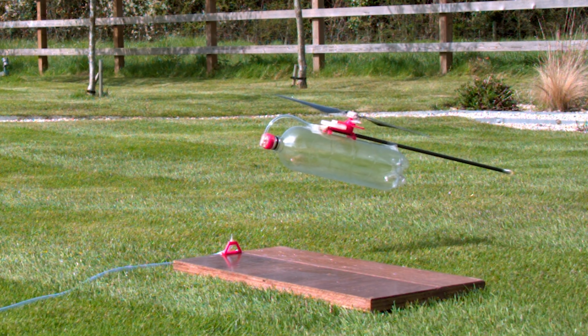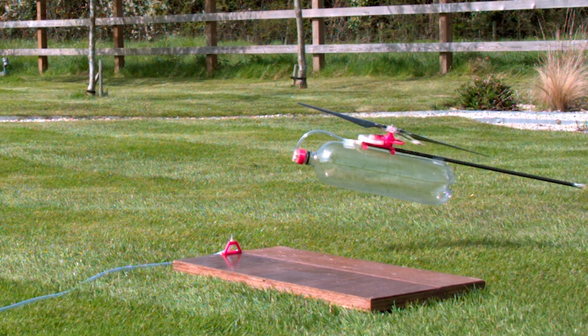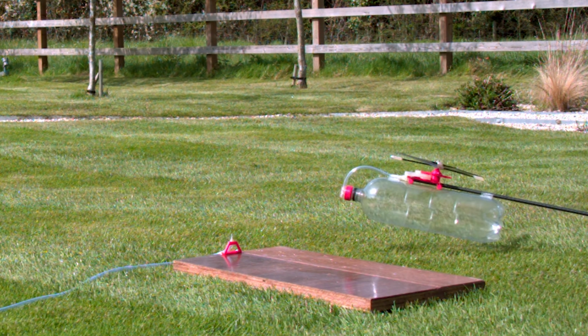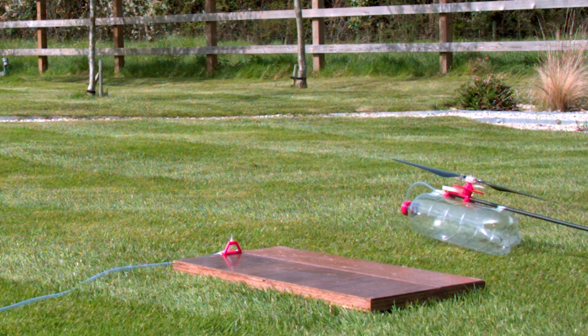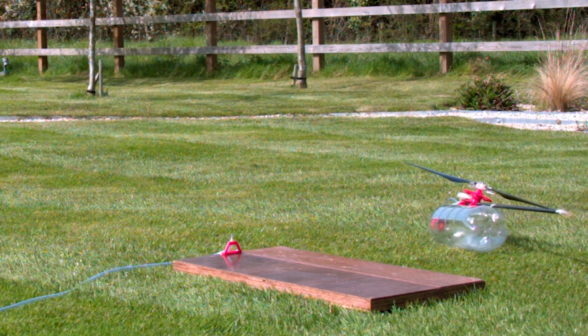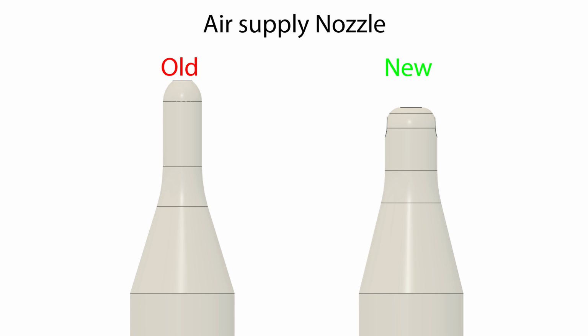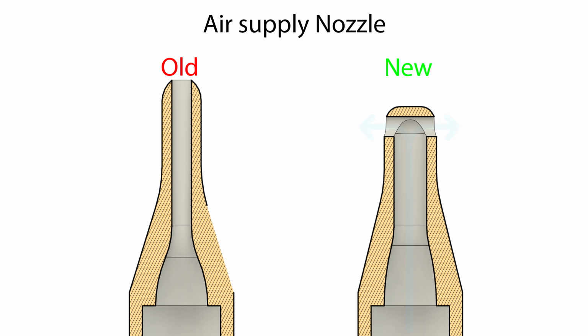I also noticed the turbine barely runs for more than a couple seconds, almost like the propeller blades are just freewheeling, which suggests the bottle isn't being pressurised. To fix both these issues, I redesigned the inlet nozzle with a larger diameter, so there is more airflow into the bottle than there is exiting via the turbine. I also designed the nozzle to vent air sideways once inside of the valve, so when the helicopter takes off, there isn't a vertical stream of air pushing upwards on the nose.